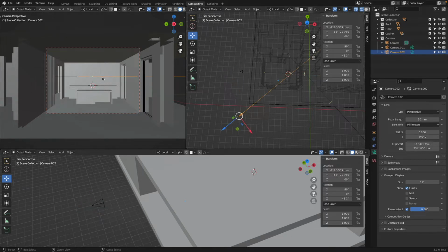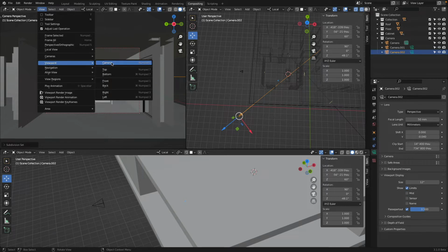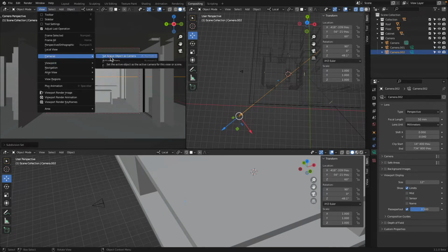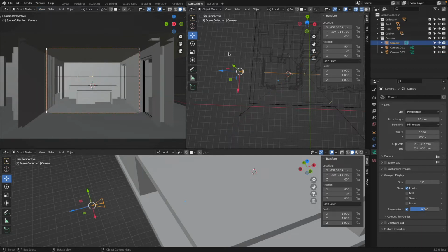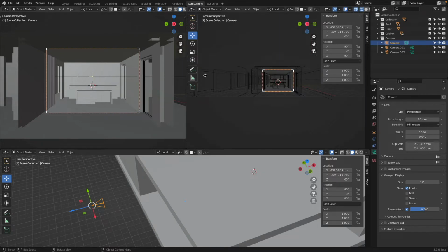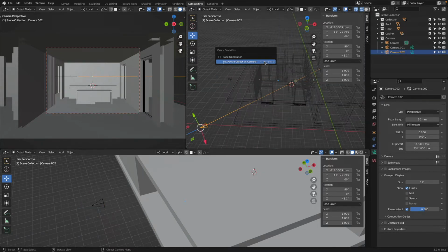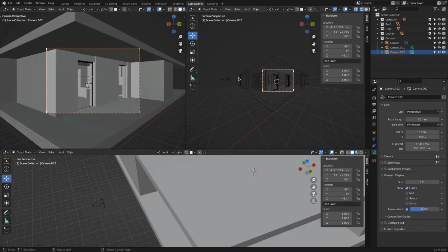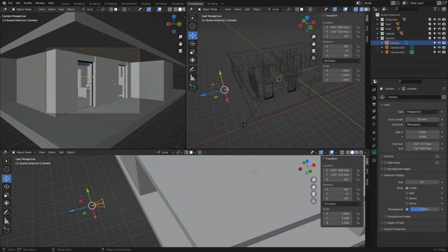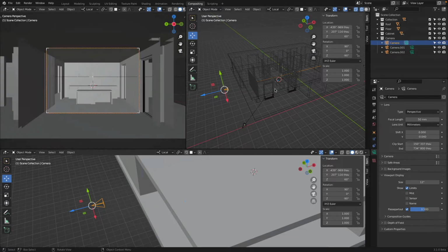Is this actually the same with that? It needs to be a numpad. So a laptop doesn't really work, but for that you simply go to here, right click. Oh, sweet. Add to quick favorites. So go to the camera, don't click, but now right click and click. So when I click this camera, press Q. Ta-da! It sets this to the active camera. So you can do it this way too.